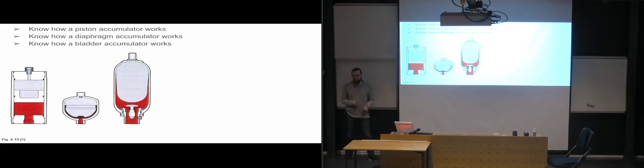If it's a spring, you could potentially have it horizontally or something and have it push in, but the springs are usually not that good in these cases, so it's often a bit better to just have this weight on top of it to push it down. And that's going to, of course, give you a certain force that you are going to expel from the accumulator when you need it in your system.